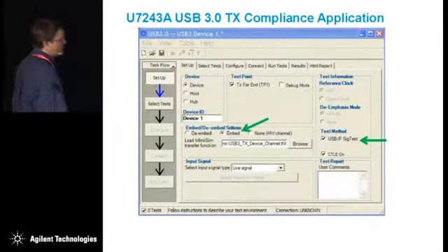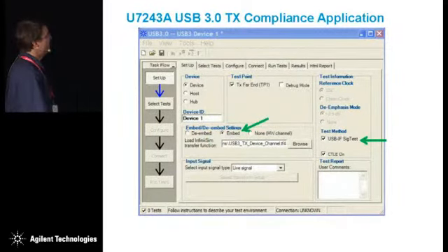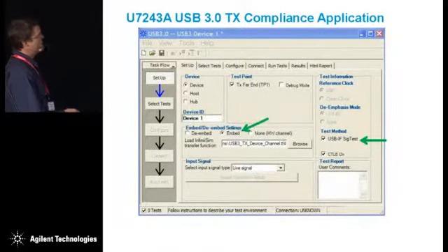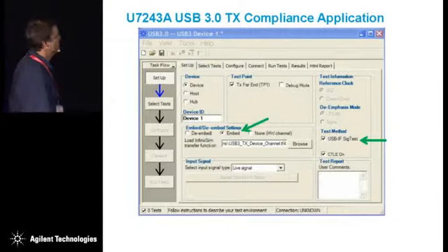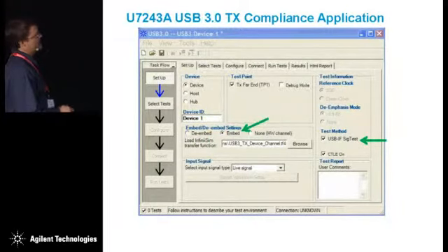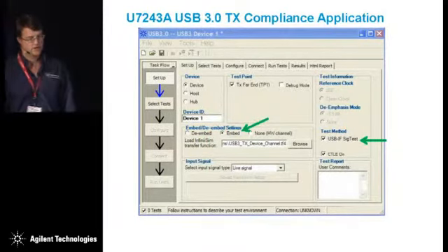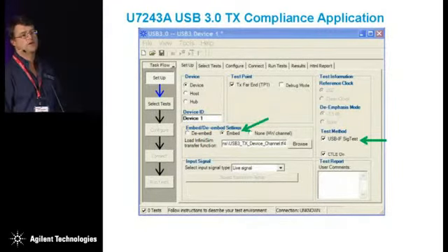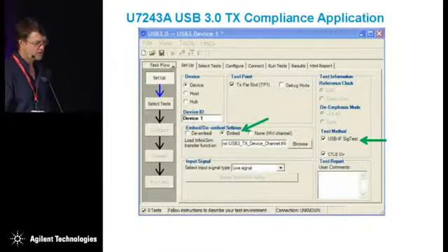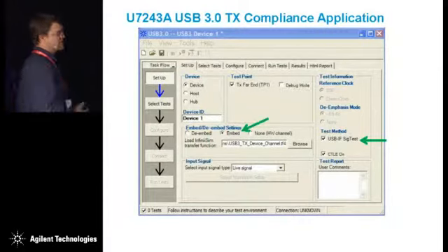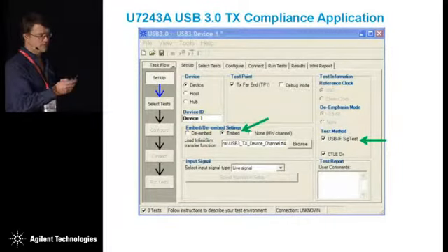Once we get that S parameter or transfer function, then as required by the Standards Committee for certification, we embed that channel effect on our transmitter measured directly through a breakout fixture that we have here. We then analyze the eye amplitude and margins and jitter and whatnot using the USB-IF SIGTEST program, which is an Intel-developed tool provided to the USB Implementers Forum as a standard transmitter test software package. This eliminates the uncertainty you tend to get between analysis packages between different vendors.